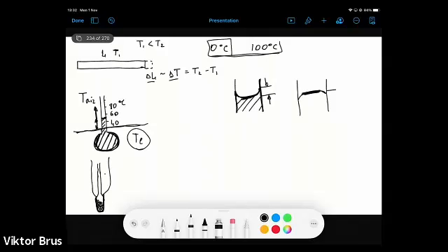Here we have some vacuum or air, and that's why even if we want to put them into contact, there will not be intimate contact, because even if we have mercury here and then we immerse it in liquid up to this level, this part still will not be in direct contact with the environment where we measure temperature, as opposed to this volume, because it will be isolated with this gap.